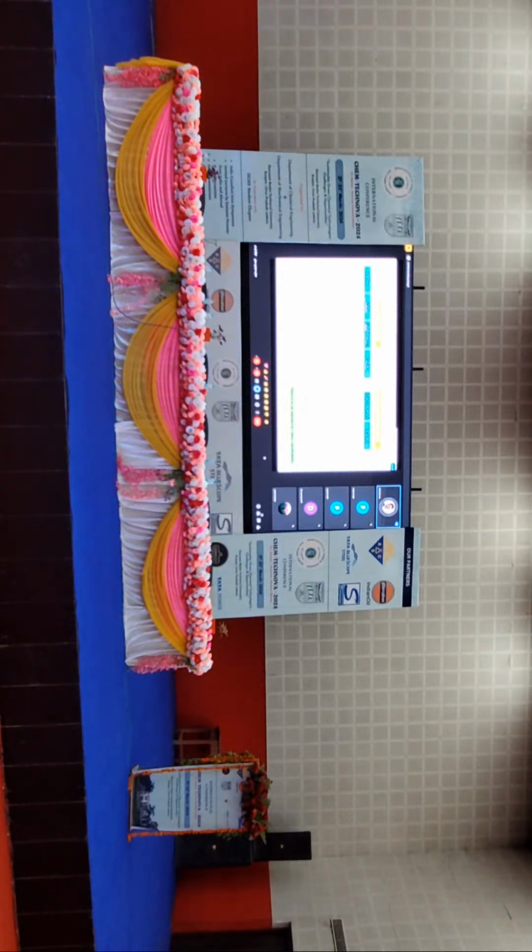But as we have seen, additional power and additional energy we can get under the mild HEV. That means the power that we can draw from the battery or utilize through the motor is around 3 to 10 kilowatts. So the motor size is increased. At the same time, the number of sets of batteries is also increased. For example, Honda Civic is having that function.